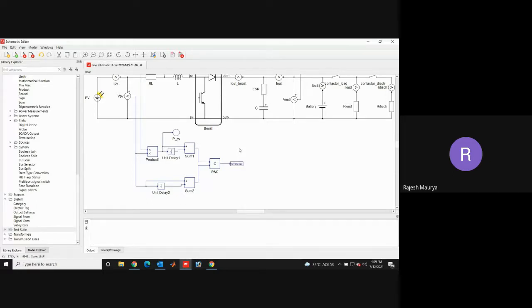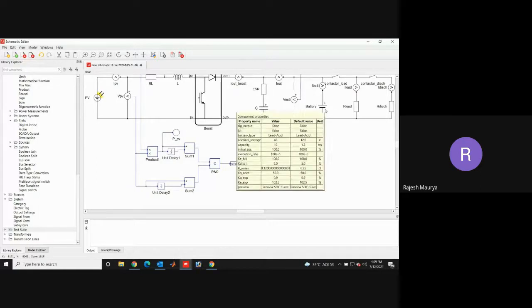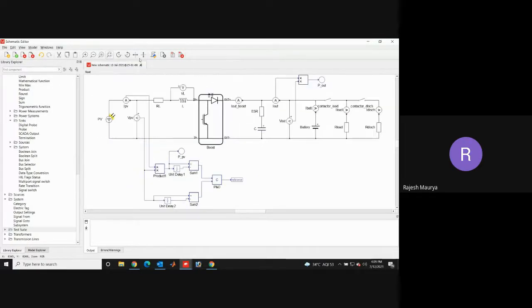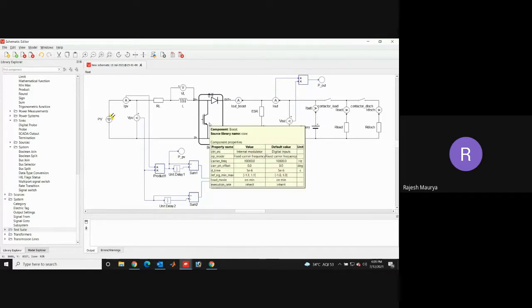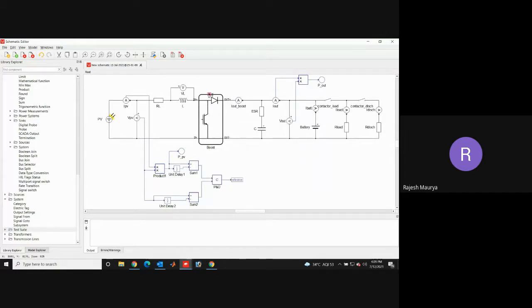Now I need to charge and discharge this battery. I'm going to charge and discharge the battery by turning on and off this boost converter whenever I require. So by enabling and disabling this boost converter, I'm going to charge and discharge this battery. First, from here, I'm measuring the output voltage. So let's take a comparator.